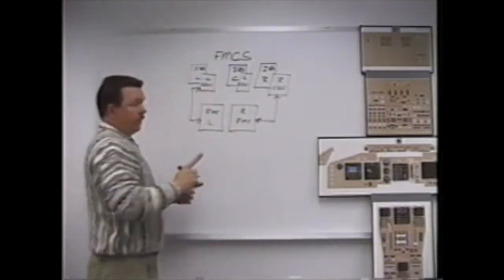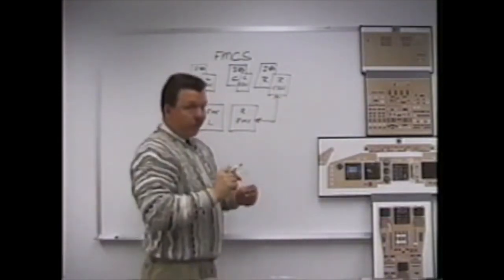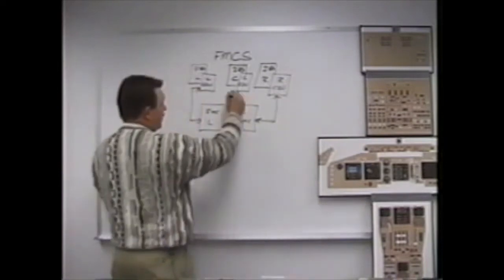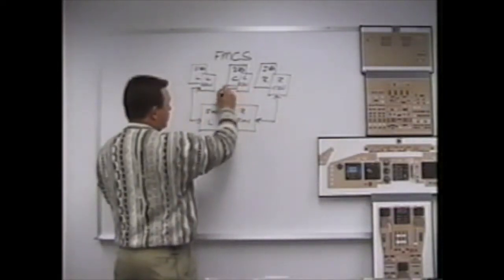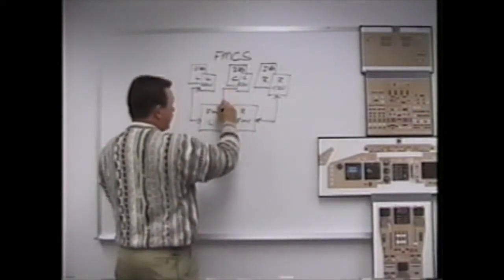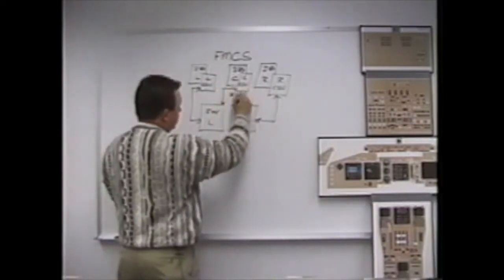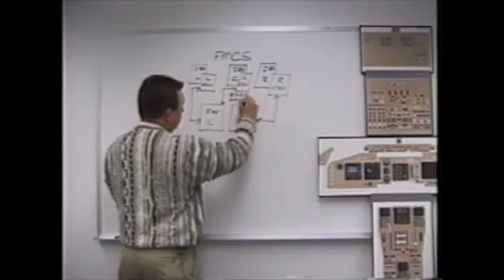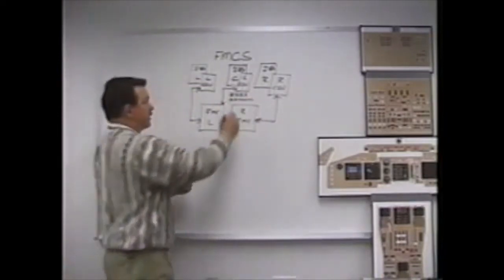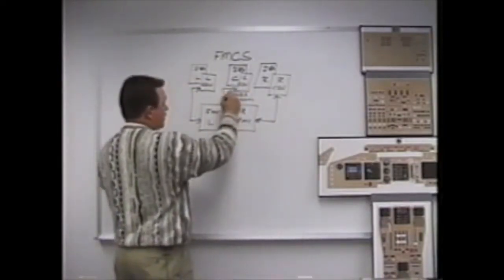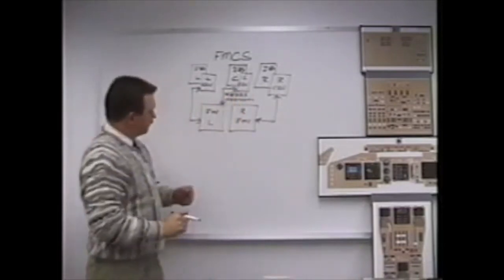Now, the center CDU cannot do FMC work. It's impossible. The center CDU is connected to the left FMC. It communicates with the left MC with ACARS and SATCOM, but no FMC. So this signal flow is specific just to these few items. All right.